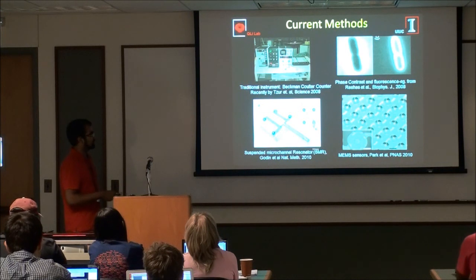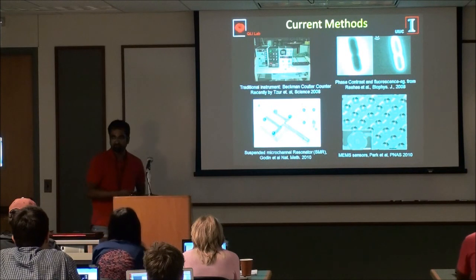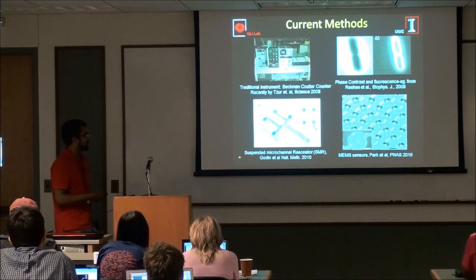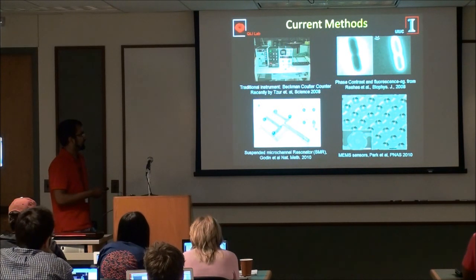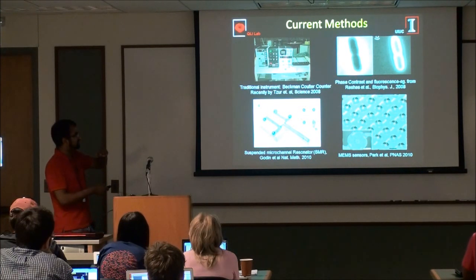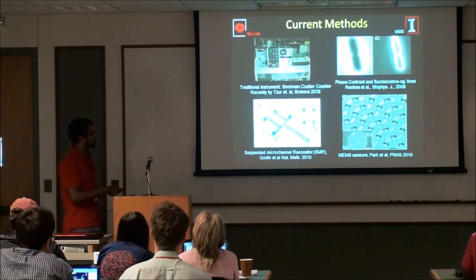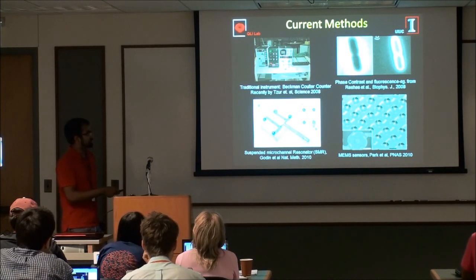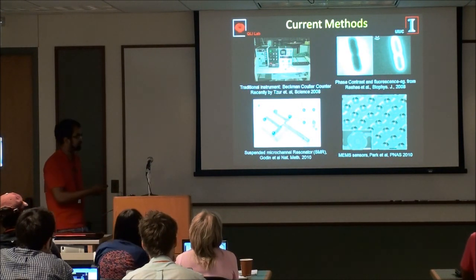The second class of methods uses MEMS technology. There has been work at MIT in which they have a cantilever system with some resonant frequency in a microfluidic channel. As you flow cells through it, it changes the properties of the resonator, so the frequency shifts, and you can get the mass from the shift in frequency. This is limited because the cells are flowing through the system, so you can't follow one cell over time, but it's pretty sensitive.